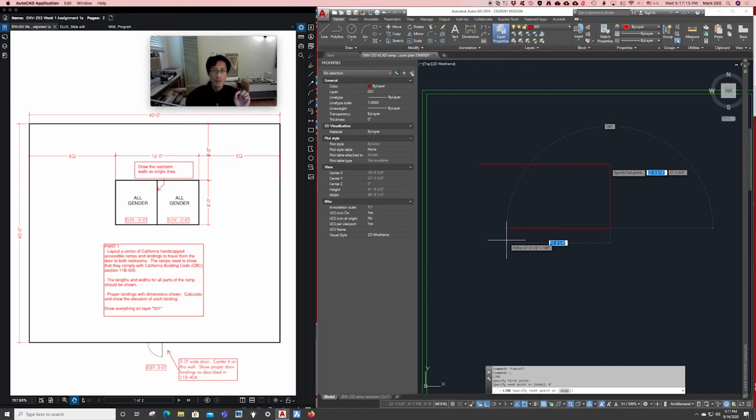When you're in imperial architectural units in AutoCAD, the actual base unit is the inch, not feet. So if I just enter a number here, AutoCAD's going to interpret it as inches. So if I want to do 16 feet in inches, I could do that, and it saves me from having to enter the apostrophe for the feet. But I don't know that conversion.